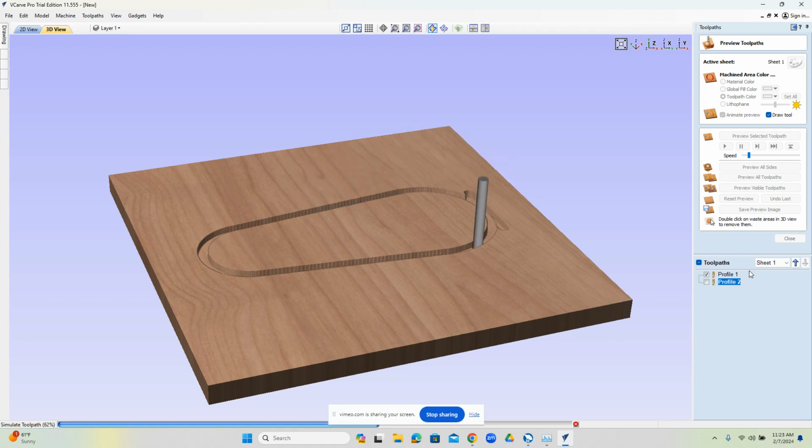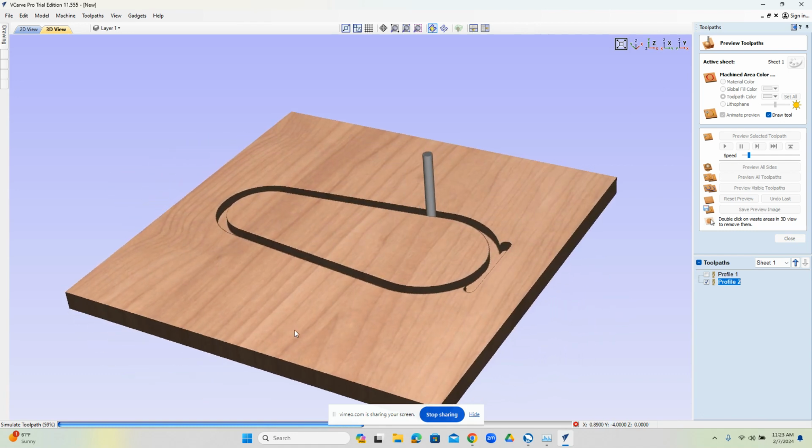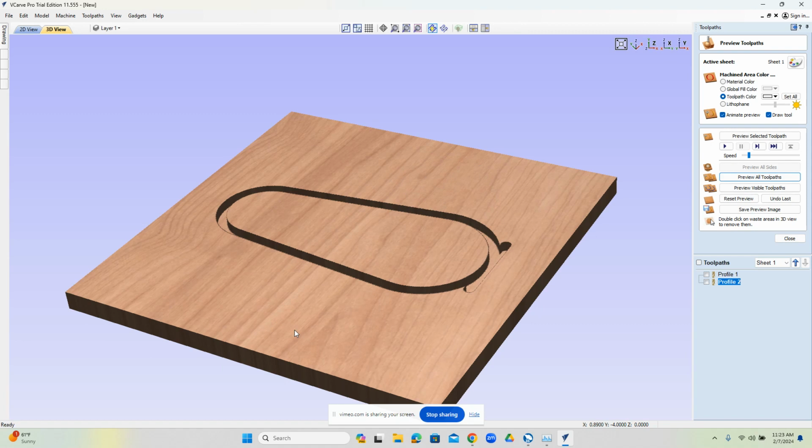Now, what we can do to kind of clean up the cut, we can adjust our speeds and feeds, slowing down our feed rate in order to get a nice consistent cut. And we've only left a little bit of material on the wall, and the point here is to give you a nice profile finish, okay? So this lead style of going past where it starts, starting off the shape and having it go past where it starts, I feel this will have a good impact on your finish, and I'm interested in seeing what your results will be.